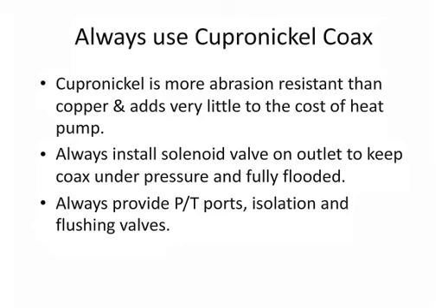Here's another always must do, folks. Always install a solenoid valve on the outlet of the heat pump to keep that heat exchanger under water pressure and fully flooded. You want to make sure of that, because if there are any metals, your manganese, your iron, things of that nature in suspension, you want to make sure it's not subjected to the air so it can precipitate out and attach to your heat exchanger, thus inhibiting your BTU transfer. So you always want to keep that heat exchanger fully flooded and under pressure, and by installing that solenoid on the outlet, you'll accomplish that.